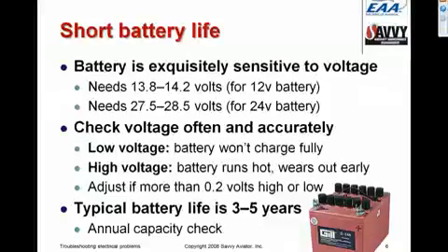You know, some aircraft just have a dedicated digital voltmeter on the panel. It's a real good idea to have something in the cockpit that lets you read bus voltage accurately to the nearest tenth of a volt, and to keep track of it and make sure that it's what it ought to be. The service manual for most aircraft has specific information on what the optimum bus voltage should be. You should look it up. Maybe you even put a little placard on the panel to remind yourself of what it is.